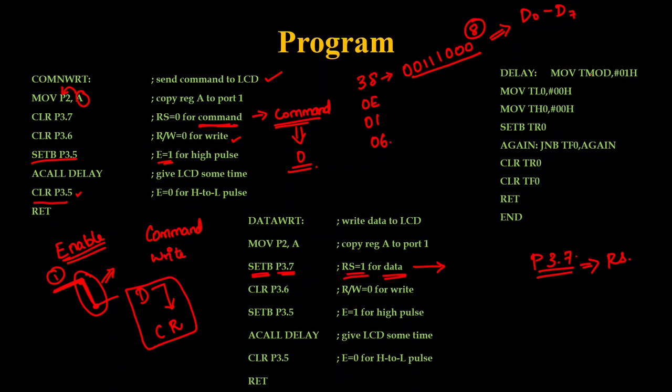Here, I am trying to create a time delay. We have seen many programs in previous videos on how to create a time delay. For this, I am activating the TMOD register. If TMOD gets the value 01, please go to the previous videos to understand what a timer is and how to activate it. With 01, you are going to work in mode 1 and activate timer 0.